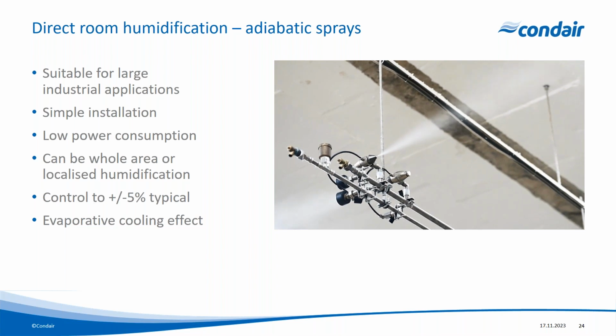Controllability is typically plus or minus 5% with these systems, so more than adequate to certainly get you over the static threshold and not raise the humidity above 60–65%. We certainly want a sweet spot between 40 and 60.